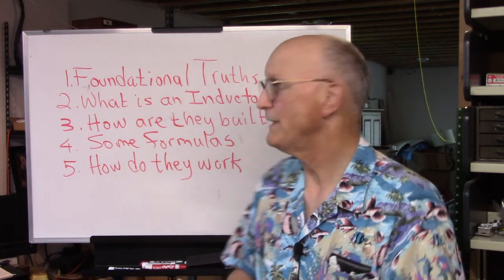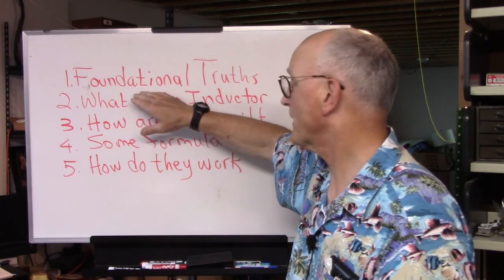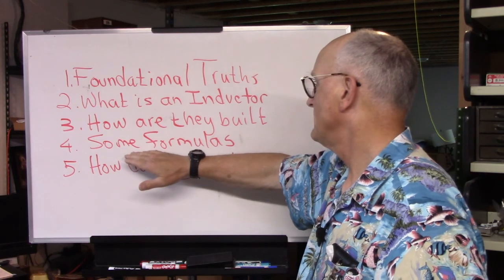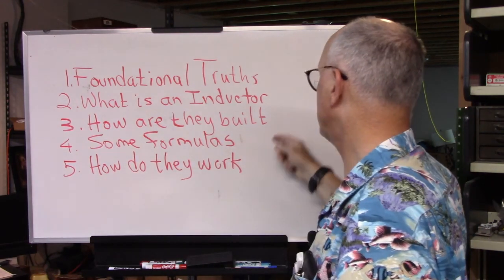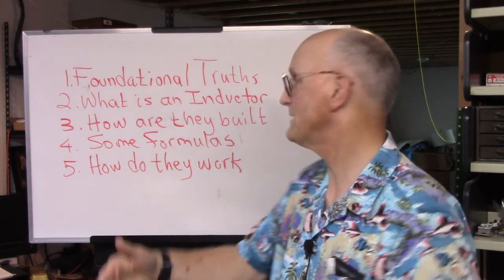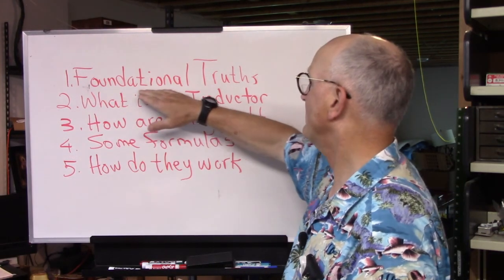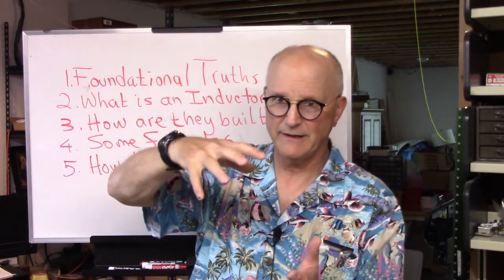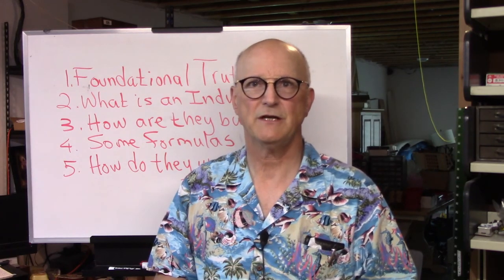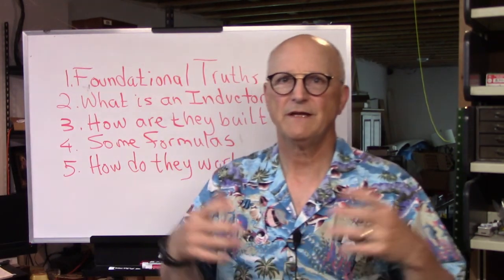I've attempted in this video to give you the foundational truths behind how inductors work. What is an inductor? How are they built? Some formulas that relate back to how they're built and how to calculate the inductance or the number of turns for a particular inductor. And then finally, how do they actually work? Taking these foundational truths and boiling them down into an understanding of how an inductor opposes the change in current.